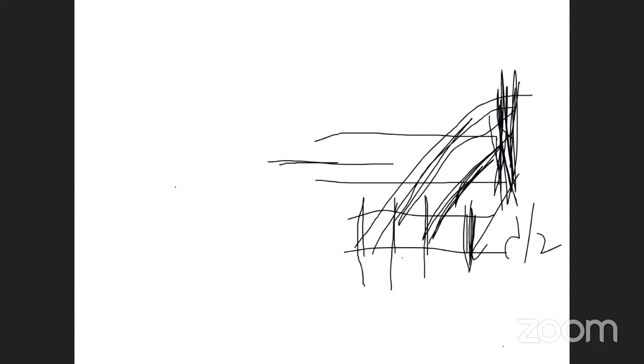Actually, the other side is closed. Again, it is returning back. This is called a standing wave. As the other side is closed, again it is coming back. So, when it is coming back, what is the status of voltage? Voltage is 0 and current is maximum. Maximum current is flowing, voltage is 0. Why is it happening like this?